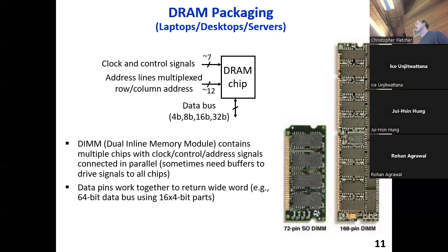You'll send a request out, and as soon as your request has cleared the wires that connect your laptop CPU to the actual DRAM pins, you'll be able to send another request out, as long as your second request goes to a different bank of subarrays on the DRAM chip. In the background, the first bank is working on your request, and it's going to return your data sometime later.